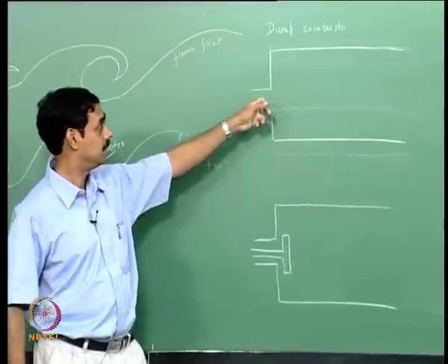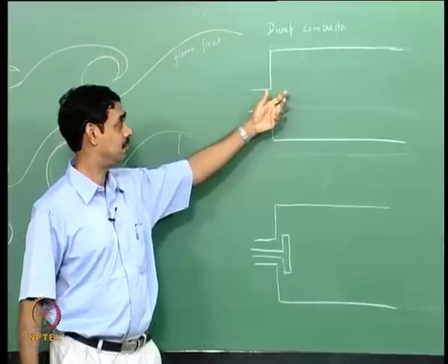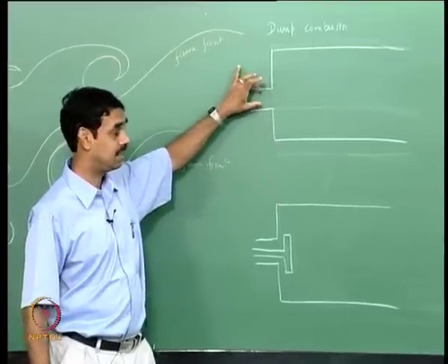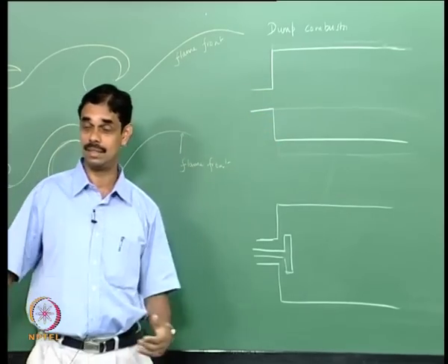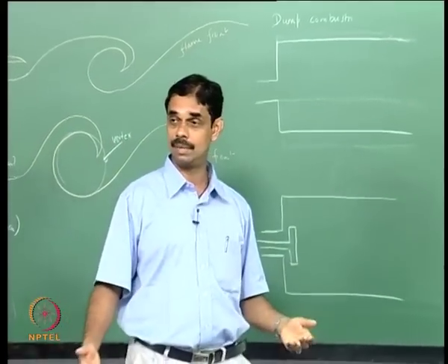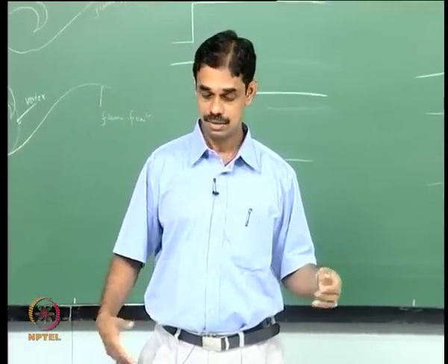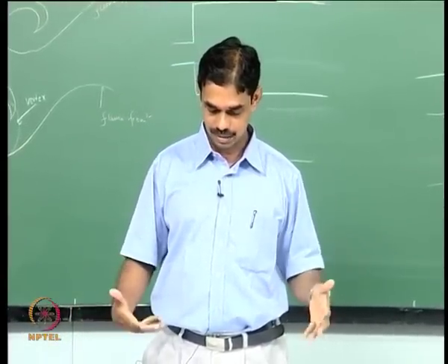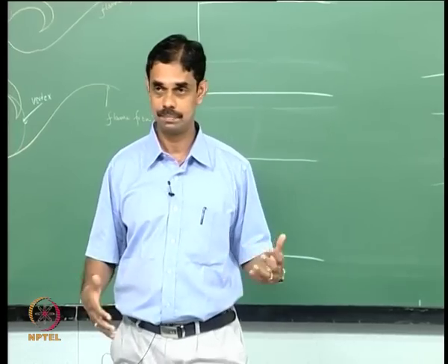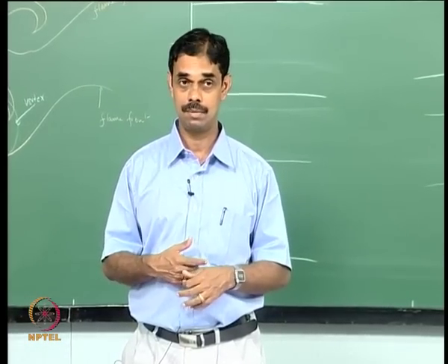So that is how, in a crude sense or in an intuitive sense, you can understand the instability mechanisms. If there is instability at some flow configuration and you want to remove it, you can change the inlet area and change the speed, and therefore you will change the frequency of the hydrodynamic instabilities, and you can make it go away from the acoustic oscillations. So this is some intuitive explanation of how a pulse combustor, or a combustor of this sort, pulses.